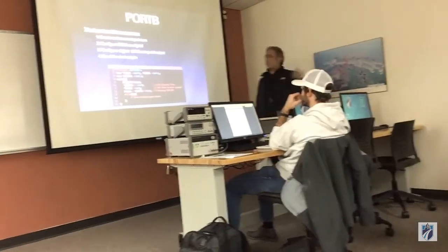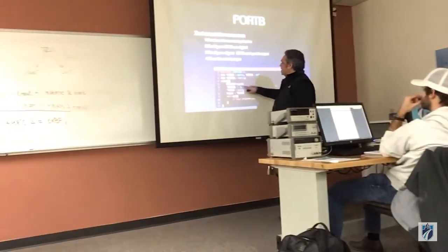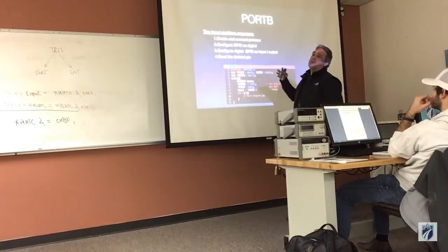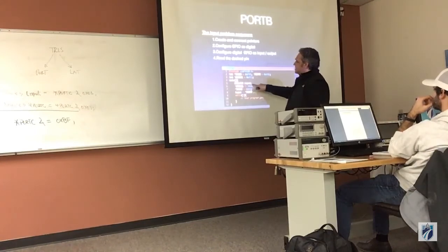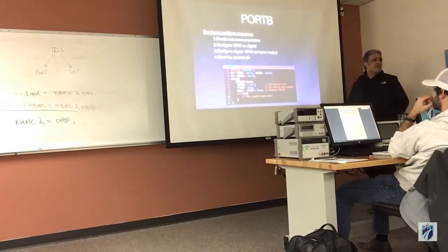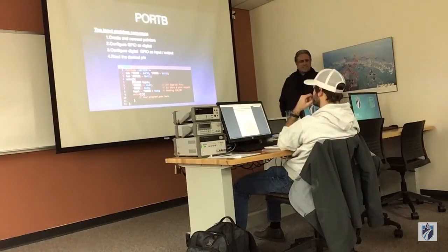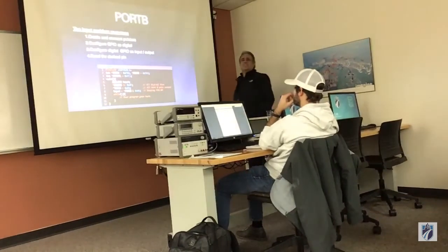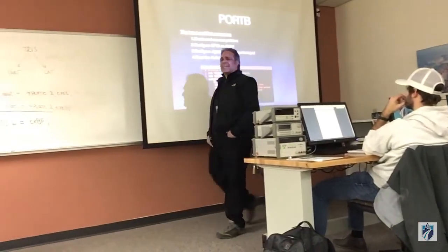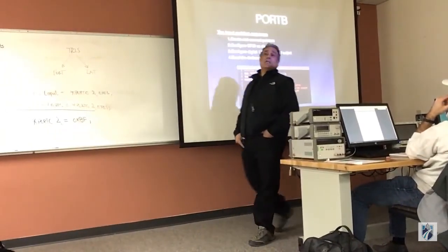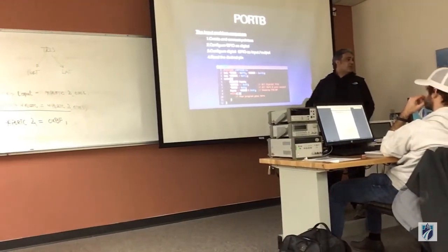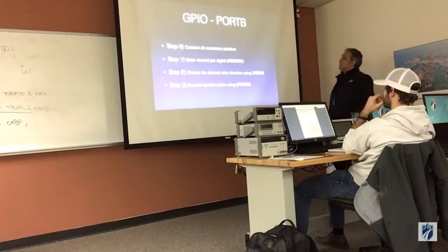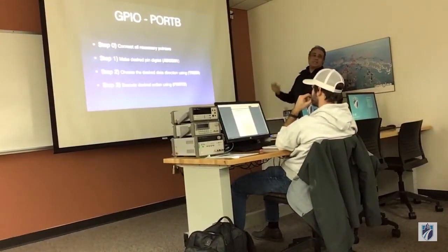One thing that you have to remember is this. This compiler in particular, or most of the low-end compilers, will force you to create your variables right there at the top. If you don't, it gives you some sort of error, I think it reads like expected identifier at this spot or something like that. It only means make sure that you declare all your variables on the first line. Don't do it after you begin executing, or the compiler will just bark at you. Okay, so that's the recipe, exactly the same as port B.